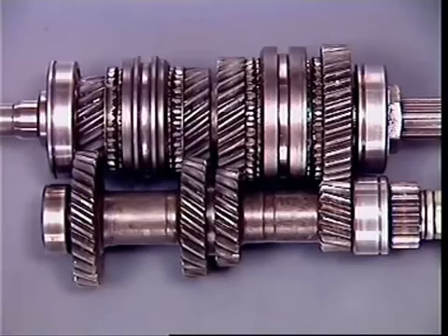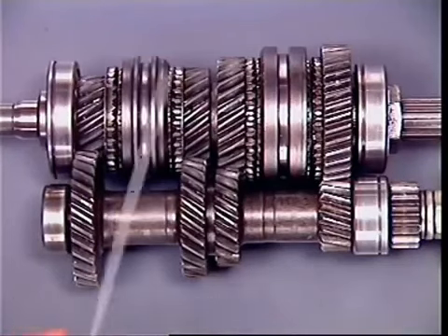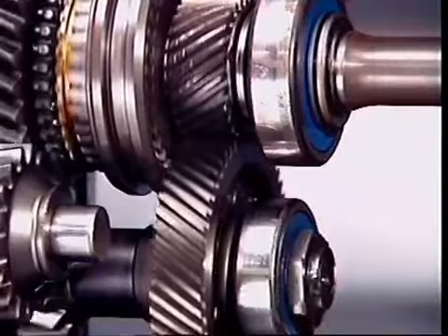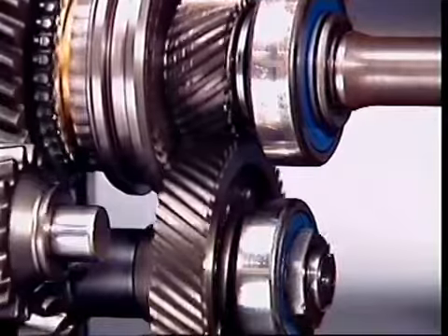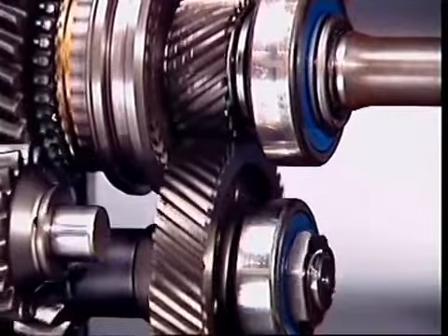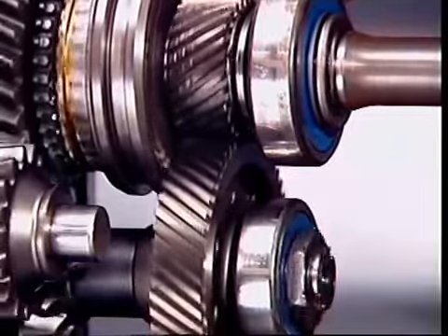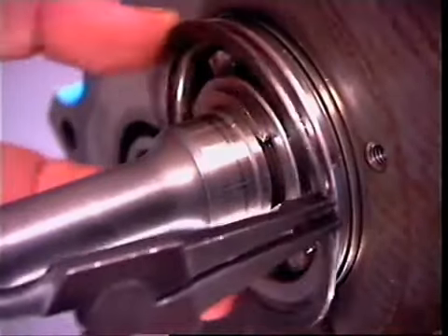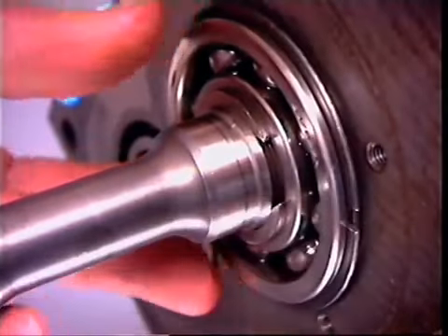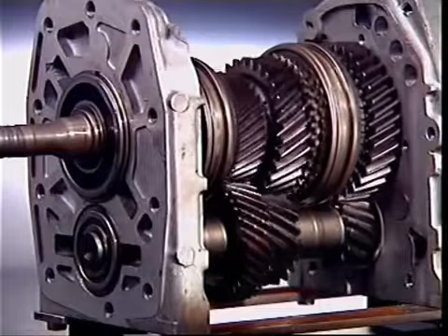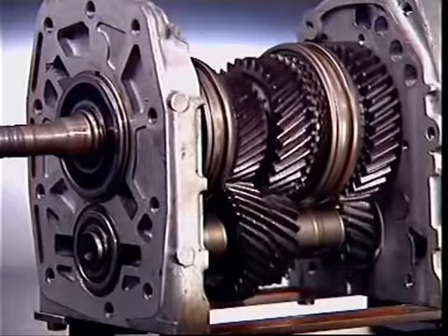Single-row, deep-groove ball bearings normally support the input shaft and main shaft in conventional rear-wheel drives. They can also be used at each end of the countershaft. The helical gearing creates radial and thrust loads as the gears try to force each other apart and move endwise. A circlip in a groove on the outside of the bearing can locate each shaft in the casing and maintain the alignment of the gears and engagement hubs.